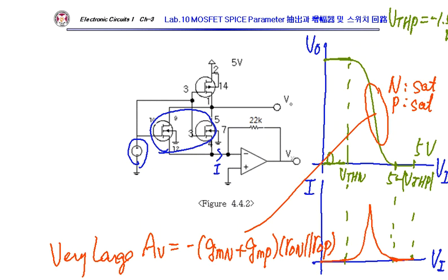Yeah, if you put two transistors here, you know, NMOS becomes smaller. So for the small VI, yeah, it matches PMOS. So let's see. Yeah, this is a 2x NMOS. It shifts toward the left. Yeah, similarly, this one shifts toward the left.